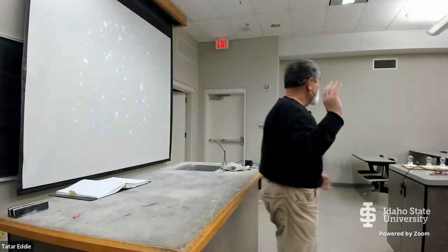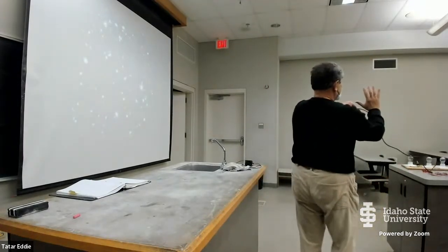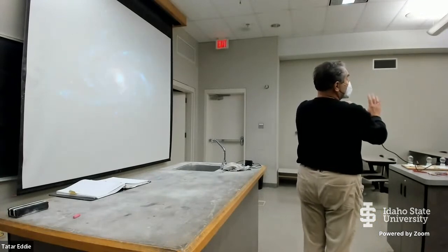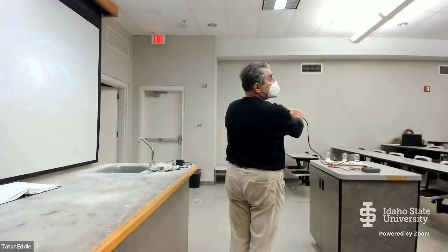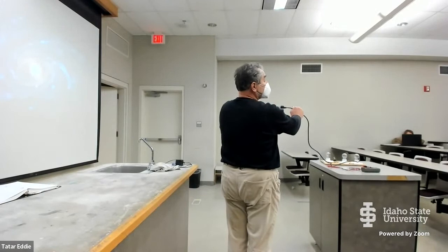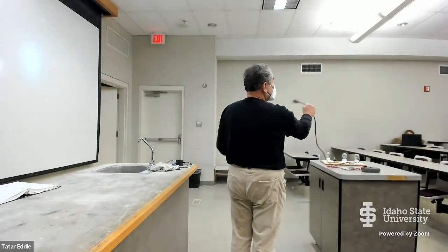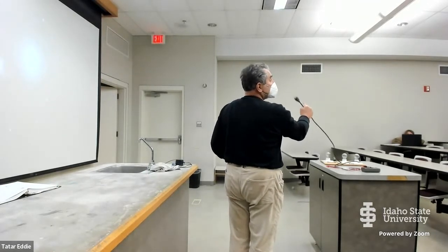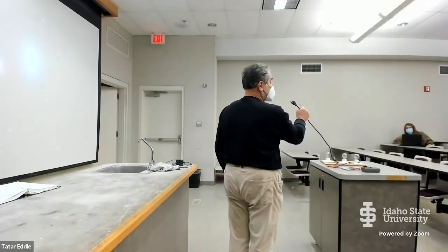So in other words, if you touch, let's say, 120 volts like this, and the current of the order of 1/100th of an amp flows through your body, your muscle may contract, and you can grasp this voltage even stronger, and you're going to have the current flowing through your body for longer time.